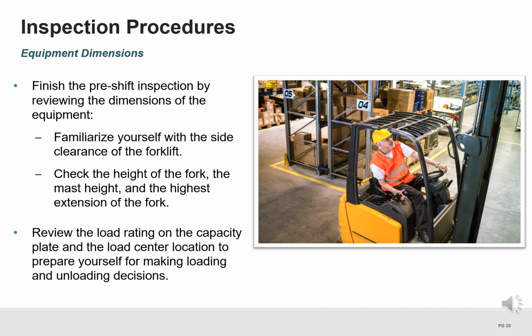Forklifts are much heavier than cars and they handle very differently. That's why driving slowly is critical to staying in control. A few things make forklifts tricky to operate. Their center of gravity changes depending on the load or attachments. They don't have suspension, so bumps and surface changes can throw them off. They steer from the rear, meaning turns feel delayed, and the back end swings wide. And finally, they take longer to stop, so always think ahead.